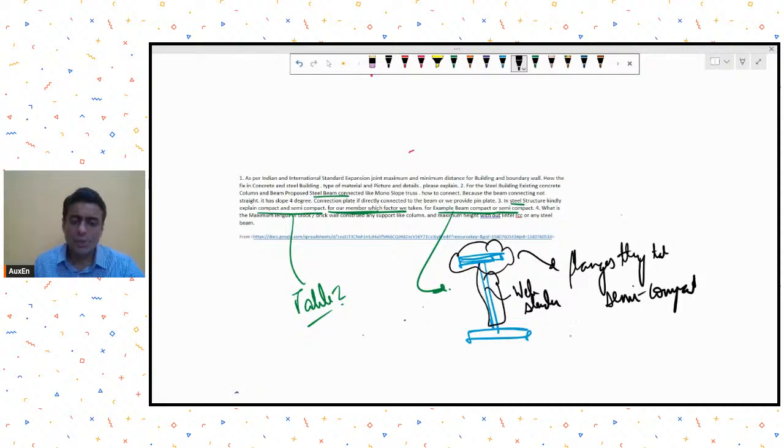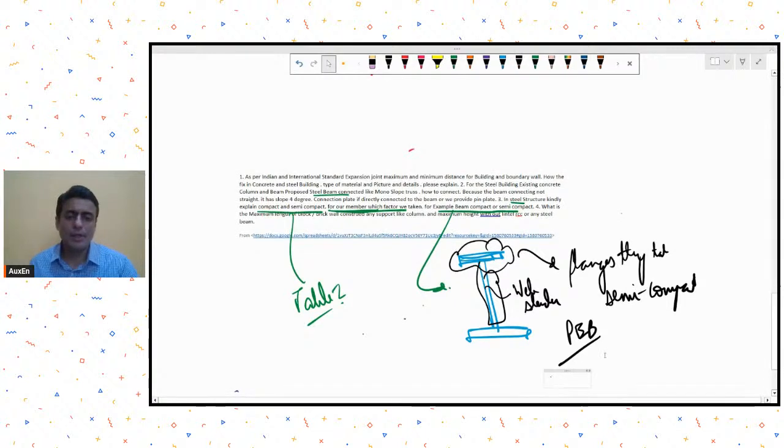So this is the usual strategy that is followed by the PEB people who are doing pre-engineered sheds, or people who are using such systems. For sections they have a semi-compact flange and slender webs. Okay, so it all depends on what sort of economy you can achieve, and that's how they decide.